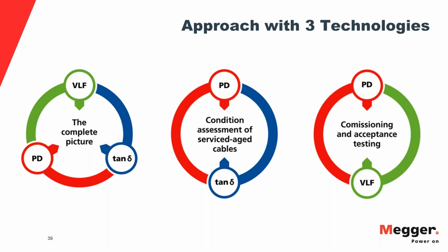Because the RMS, as I showed you, the cosine rectangular and the sinusoidal are very different in waveform. But RMS is something that is related to the energy that is going in and coming out of the system, so it's comparable. And I didn't explicitly mention this: if you do a VLF withstand test with sinusoidal and cosine rectangular, and you do it to the same proper test parameters, the outcome is the same, okay?